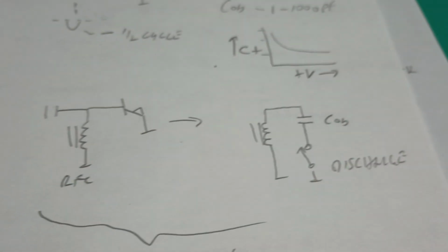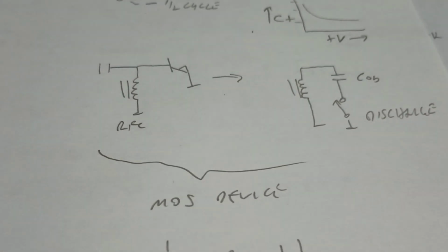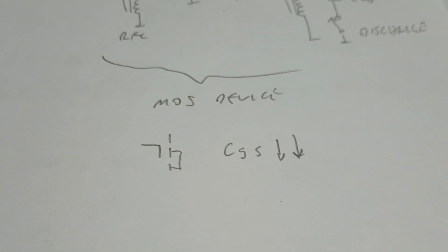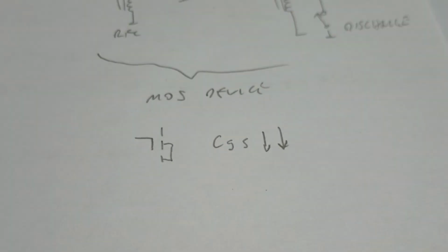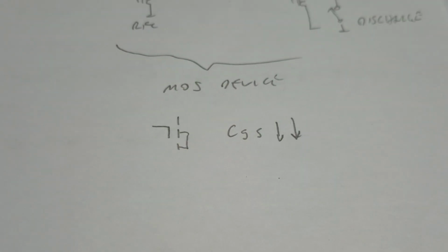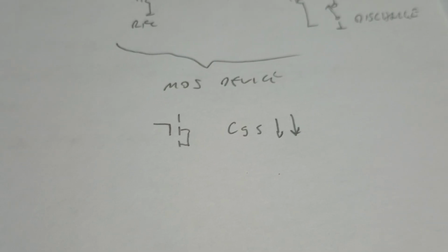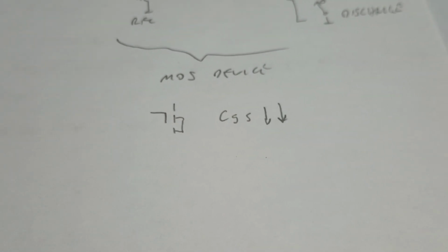So that's okay for low power and low frequency, but modern practice is to use MOS devices, which have extremely low capacitance, on the order of maybe a couple picofarad at the most, because of the way the gate to source region is made. So these are the puppies that tend to be used for RF power applications above a few watts.